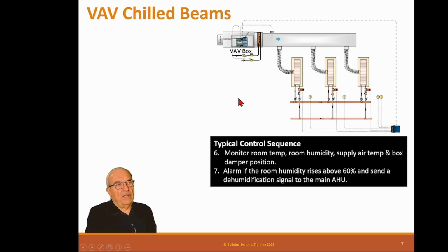All right, before I leave chill beams, I guess I'll explain the name. The reason these are called chill beams is because it makes no sense at all, right? They're a coil in the surface. Well, in Europe, when they ran into that problem of the chill ceilings not having enough space, they actually built some box beams that ran through the space below the ceiling, and they put chill ceiling panels on all four sides of this beam, and they called them chill beams. And that's where the name came from for chill beams. They then adapted it to these diffusers with coils. That's why they're called chill beams.